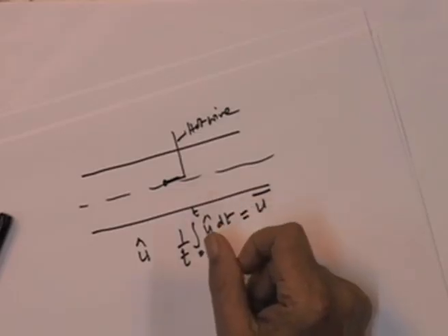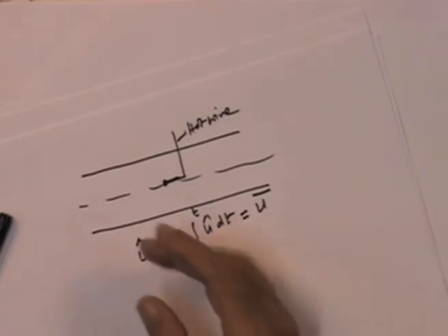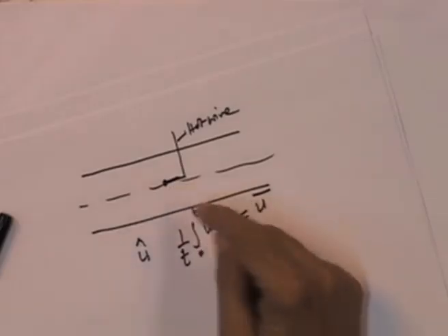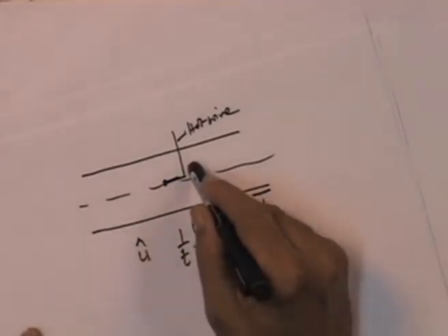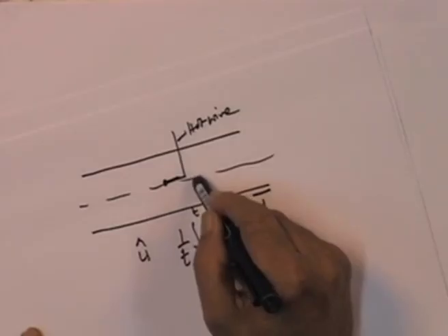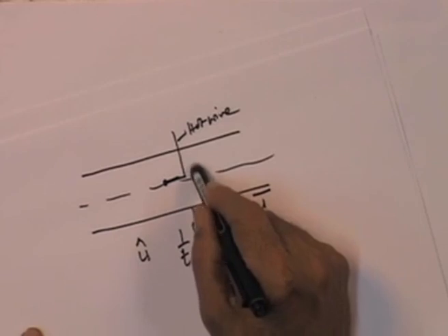Now, of course, as you all know and have experienced, supposing I were to turn this pitot tube to face in the radial direction, then because the flow is fully developed, the mean radial velocity will be 0.